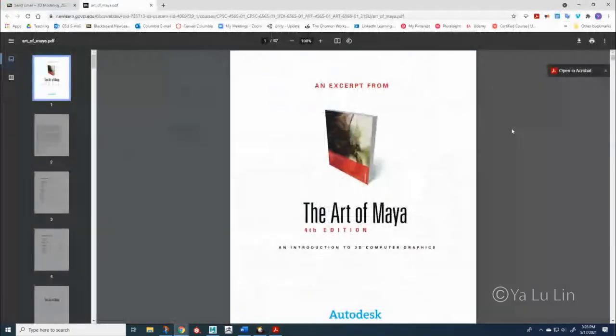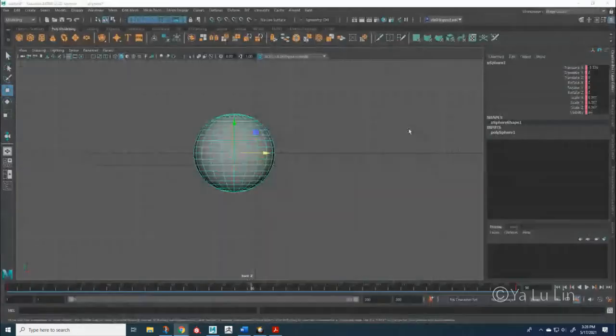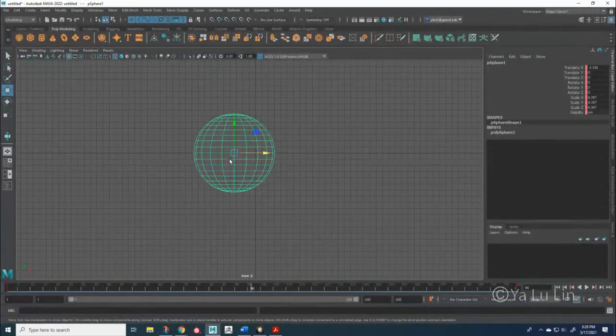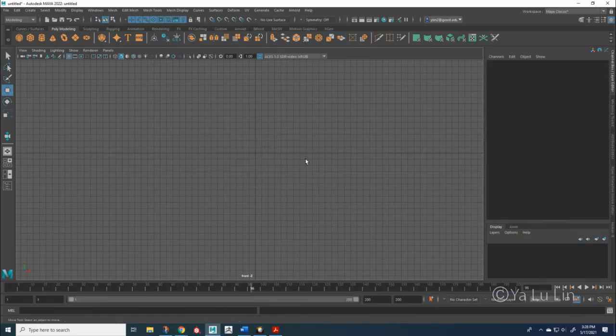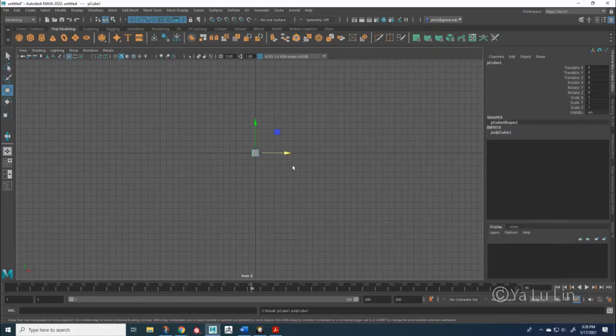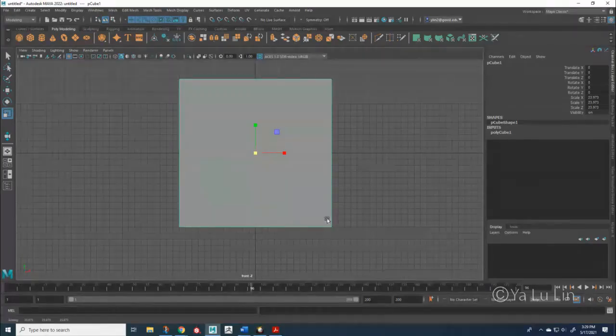Okay, let's try that inside of Maya. If I am in number 4 mode, I'm looking at wireframe. If I press number 5, I'll be in shading mode. Number 4, wireframe. Number 5, shading mode. Now, if I go ahead and bring out, say, a cube, and I select this, you can use the right mouse marking menu, right mouse click. Say I'm in object mode. I'll make it bigger. So this is what the object looks like.